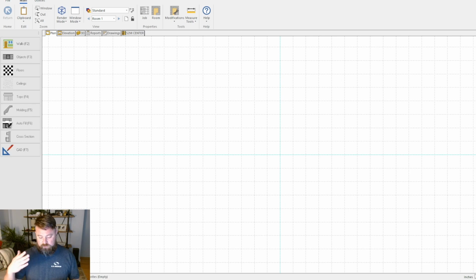What you set your precision level at is what you are going to see as far as what Cabinet Vision tells you certain numbers are. For example, if I have a very loose rounding, let's say I go to a 1/8 rounding, which is not very accurate, it's not very precise. If I have my precision set at something like that, I could have a measurement of, let's say, 4 3/16. Cabinet Vision is going to say, well, he's got his precision set on 1/8 inch units, so it might round that up to a quarter instead of 3/16.